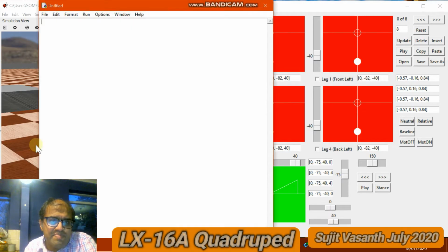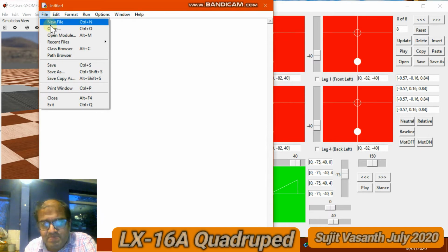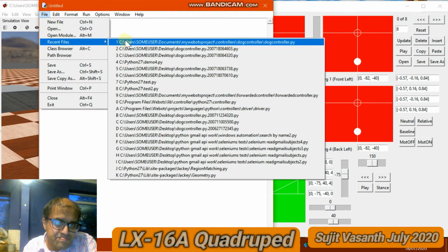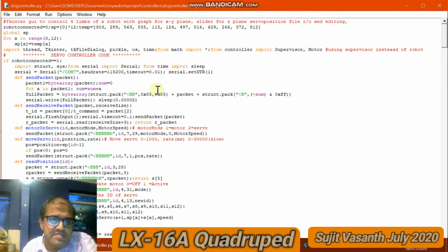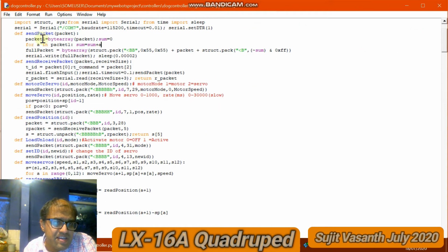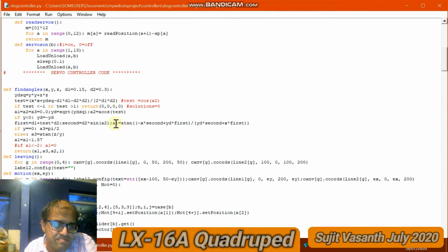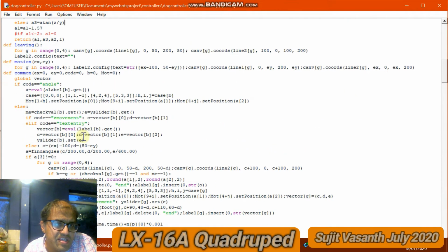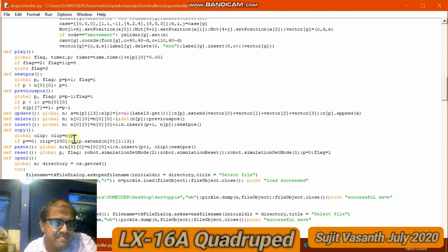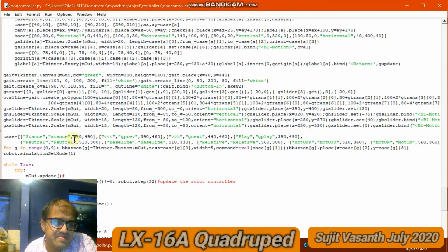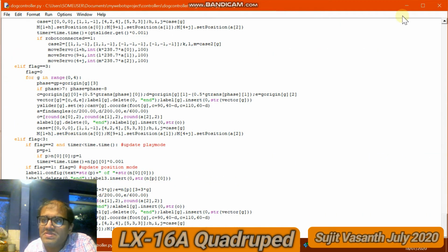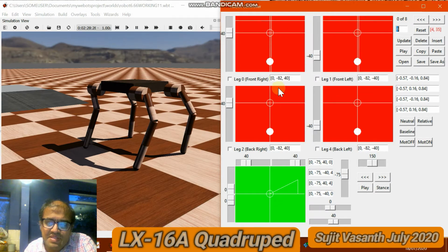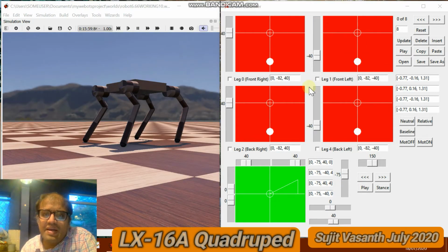I also have my Python program which produces all the display on the right side, and that's here. So this is the code I've written. It has a servo generator. It has an inverse kinematics section, and then it has a gait player, which is this section here. But the robot and everything's running here. So this is a demonstration of using my gait generator, which is here.